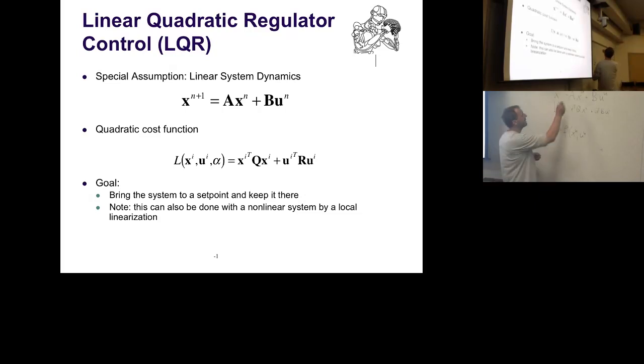If you do this, then A actually starts to depend on n as well, since it changes from time step to time step. But it's totally doable. And if you do that, you can basically solve nonlinear optimization problems with the same idea. Now, we are currently bound to having these quadratic functions here. That is important. So we can only be quadratic in the states and quadratic in the commands. We cannot do nonlinear terms in the ILQR, otherwise we can't solve the problem.